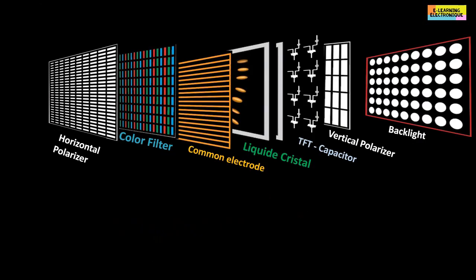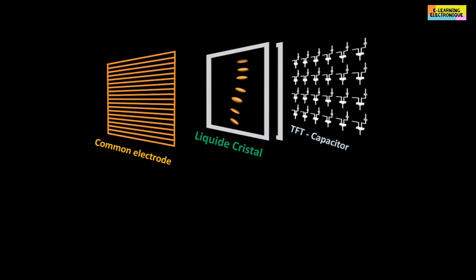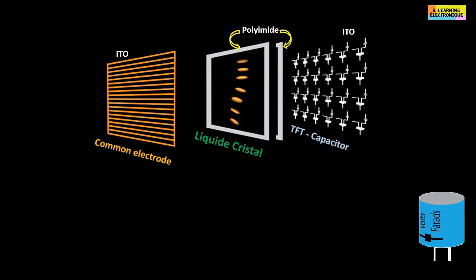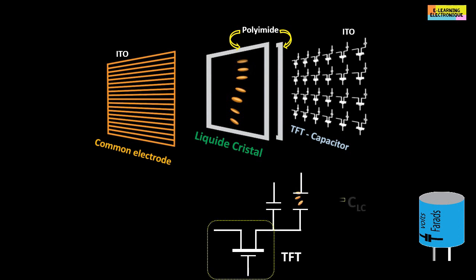To understand the role of the different gamma voltages that will go to the driver source chip, we need to go back to some notions seen in previous episodes concerning the properties of the liquid crystal. The latter is assimilated to a non-polarized capacitor because in its architecture we find all the ingredients of a capacitor with a double conductive armature made here from a transparent conductive material called ITO. These two armatures are separated by a double insulating layer based on polyimide and between which the liquid crystal is trapped. As this liquid crystal capacitor does not hold the charge properly, a real capacitor has been added in parallel to hold the charge until the voltage change on the liquid crystal capacitor.